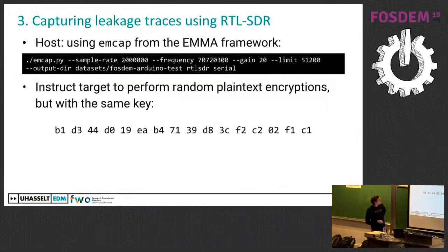Okay, so now we need to actually capture the traces. We just used ChipWhisperer to perform random encryptions, but we still need to capture them and store them in a certain data set. For that, I developed a small tool which is called MCAP. It's part of the EMMA framework, and it's basically just a wrapper around GNU Radio blocks.